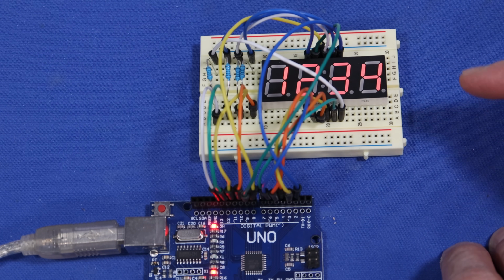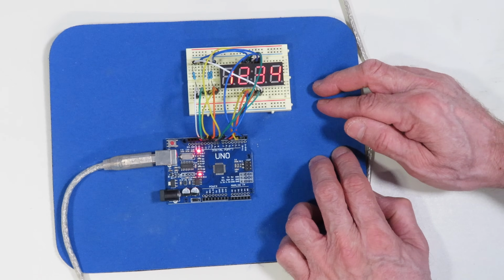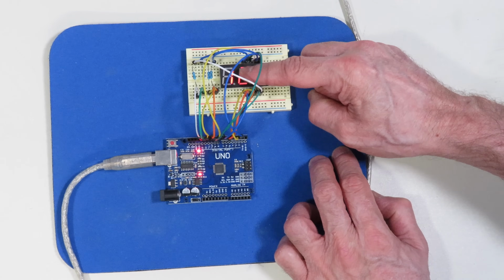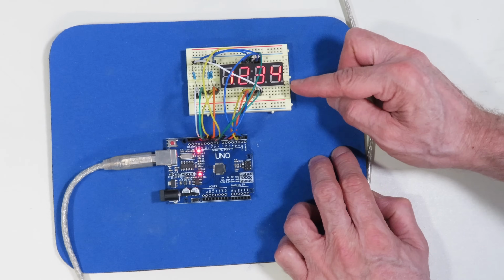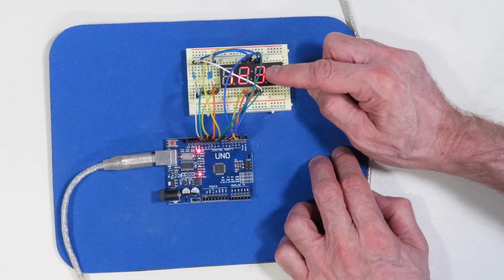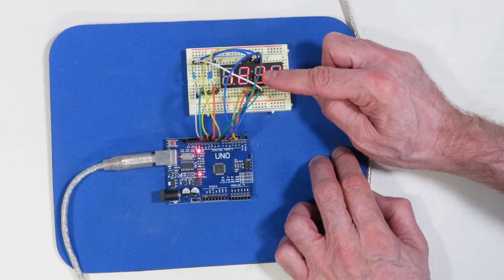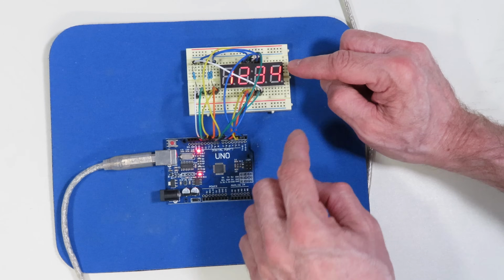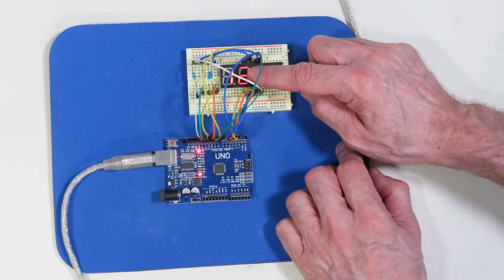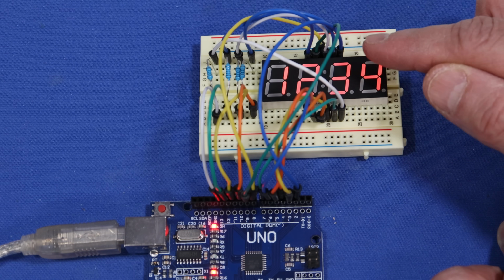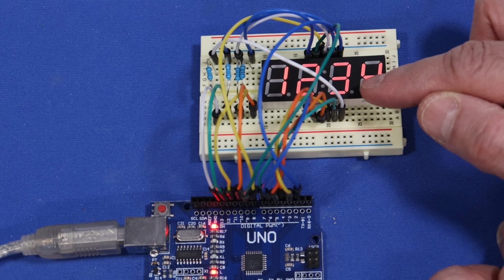Now as a result, this does have a bit of an effect that you can't really see on the camera, because I think the camera's compensating for it, but I can see it myself right now, and that's that the number 1 is quite a bit brighter than the other numbers over here, and that's because of course the number 1 only requires lighting of 2 different segments, and so it's got the current all being divided between just 2 segments, where something like a number 3 uses 5 segments, and that same amount of current is being divided 5 ways.